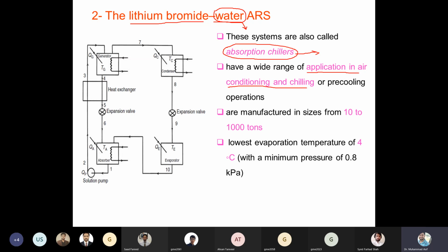As we are doing in GIK, we are producing the chilled water in the HVAC system, and that chilled water is sent to various buildings where they have installed the air handling unit, I mean the cooling coil, as a heat exchanger between the outside air and the chilled water. Then the cooling air can be produced in various buildings. Similarly, during the winter, the hot water is sent to the buildings and in the air handling unit, as a heat exchanger, hot air can be produced. Anyhow, we are talking about the application of solar energy for the cooling system.